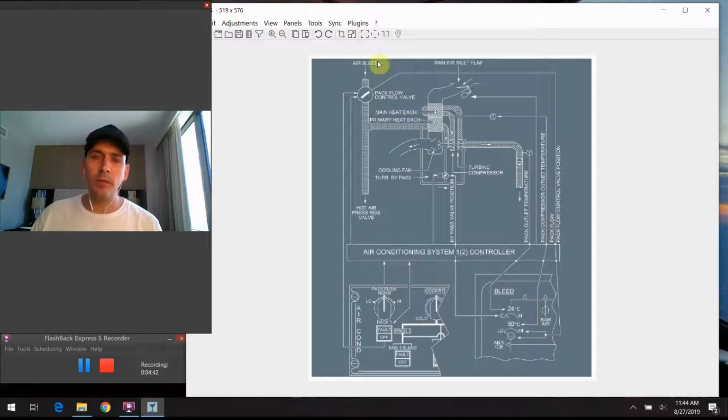So, once again, the high-pressure, hot bleed air comes out of the engine and goes through the first section of the pack, where it runs over this heat exchanger and some of the heat is extracted. Then it routes through this compressor section where it gets further compressed, and that air is routed again over another portion of the heat exchanger, so we take more heat off. Then it twists its way around and makes its way through this turbine expansion chamber where the gas is allowed to expand, like we said, and becomes very cool at this point. Then it gets routed out into the section of the pack where the cool air comes out, and feeds into the system there. So that is a very general, high-level concept.